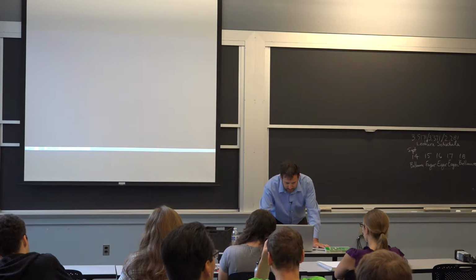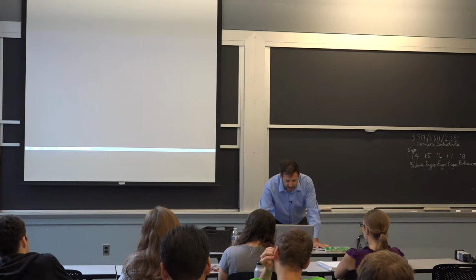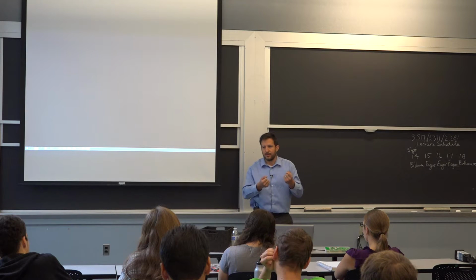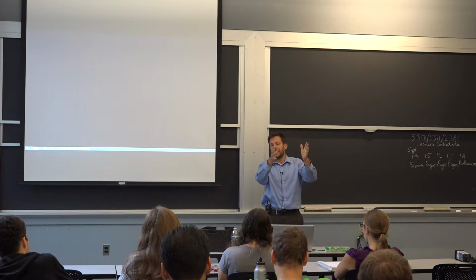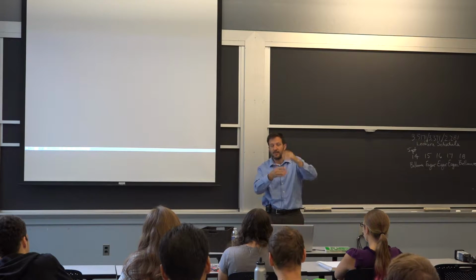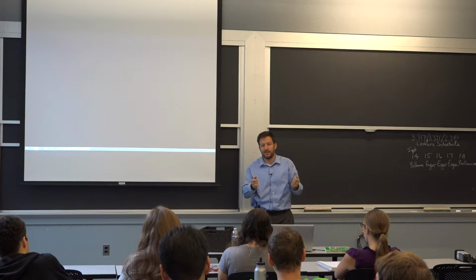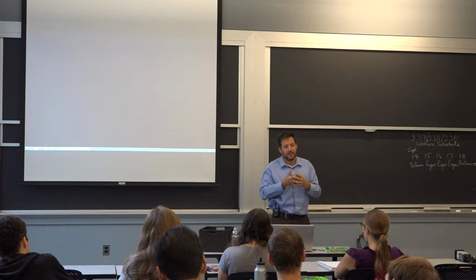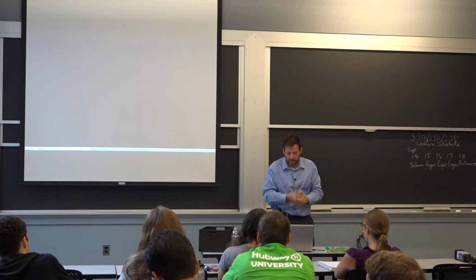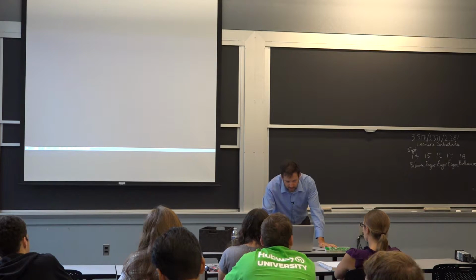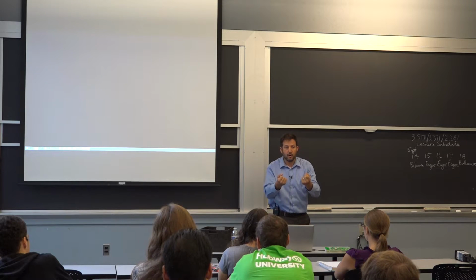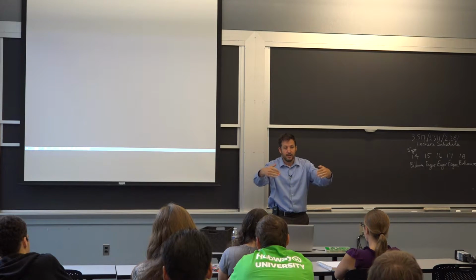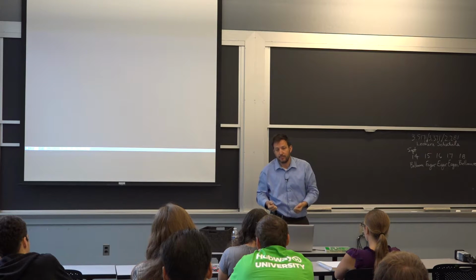And this video here goes in great depth, because one of the big criticisms of this pulling theory was, okay, well, why did it tip over? Why did the entire tower tip in the end? That sounds like a buckling, and so that sounds like it's the main column that failed first. And I think the final rebuttal to that was, well, yeah, one side pulled more, and that's the entire wall that buckled because of the pulling action.